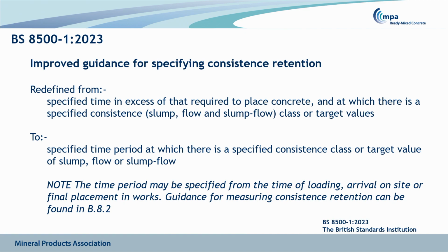The main change, though, is in the note, and this allows the specification of consistent retention to be from the time of loading, the time of arrival on site, or the time of final placement in works. So you can define this depending on the use of concrete, depending on what the specifier needs.